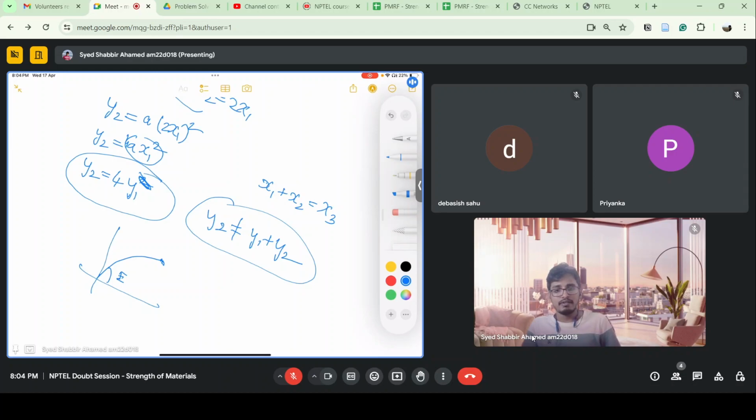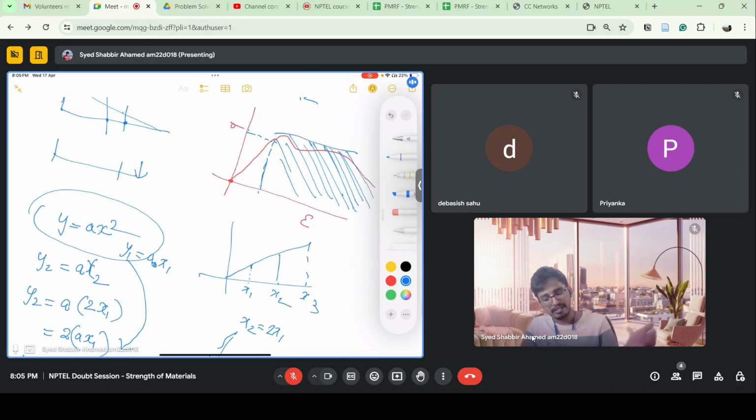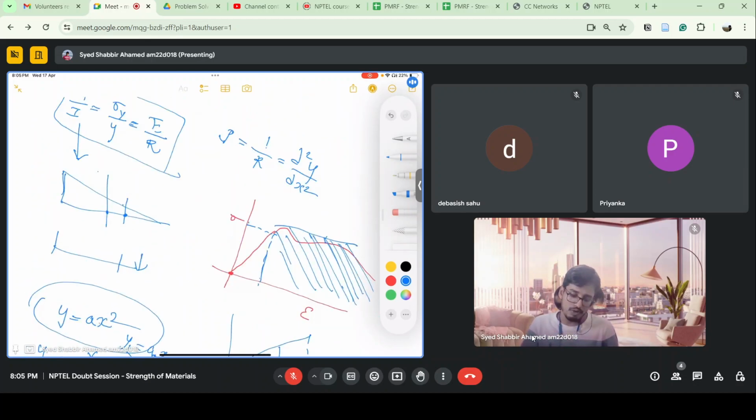Depending upon the material, depending upon the load condition, depending upon the structure, we have to do analysis. So civil engineering people want to stay in linear zones, but even though you want to stay in linear, it is just an approximation. Sometimes you want to save material and you want to go to that zone also, because failure is not happening, right? The material is very ductile, so I can use the property till this zone.